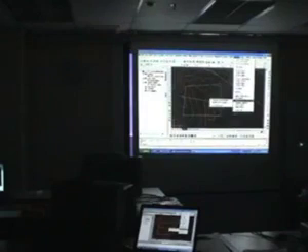Okay, that's the grid volume method. The second method is the composite method, which can only be done by the software. It's not possible to do this manually. A lot of people also call it the DTM method. DTM stands for Digital Terrain Model. This takes a direct comparison from your original ground level to your proposed level, and you get the volumes from there directly.